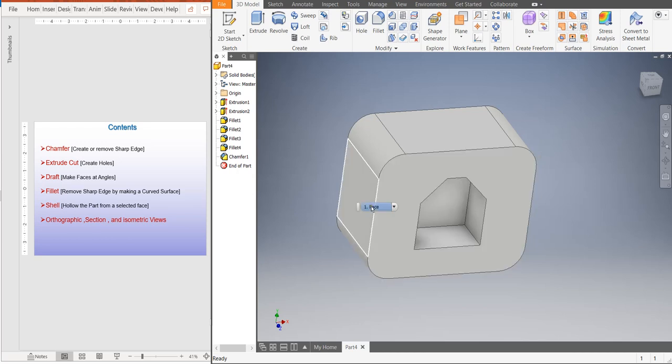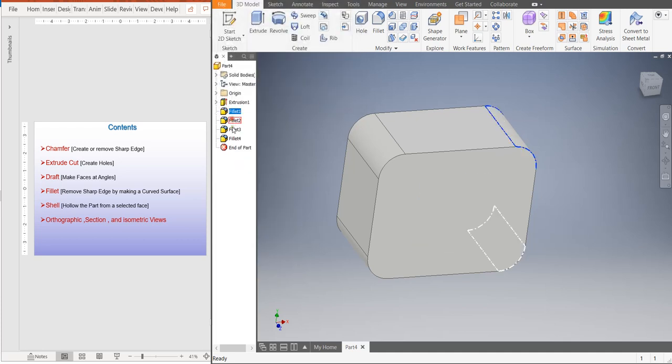Say that I want to remove the inside extrusion. I will right click here, delete this extrusion, delete everything related, and come to this fillet. I need all of these, so I keep them. Now we have a command called shell.